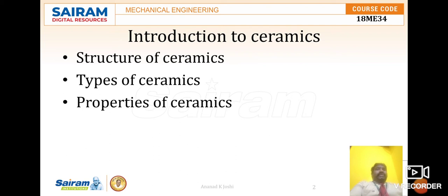Considering engineering or advanced ceramics, these materials are made from synthetically produced raw materials like oxides, carbides, nitrides and many others that offer superior properties and make them suitable engineering materials for applications. They possess high purity, such as 99.99%, and can be made available in a small and uniform particle size, leading to large surface area and high reactivity, and above all reproducible processing characteristics, that is, homogeneity, with intentionally added impurities like dopants.